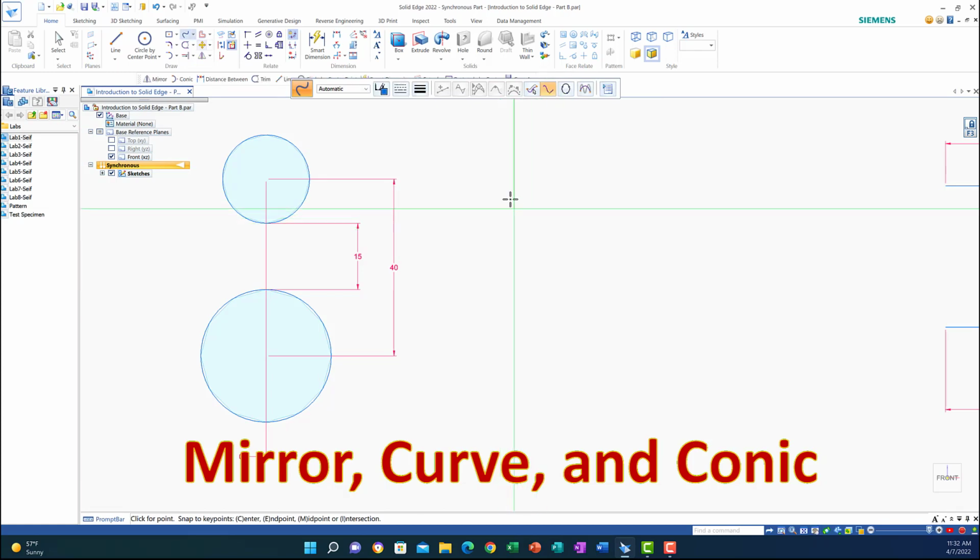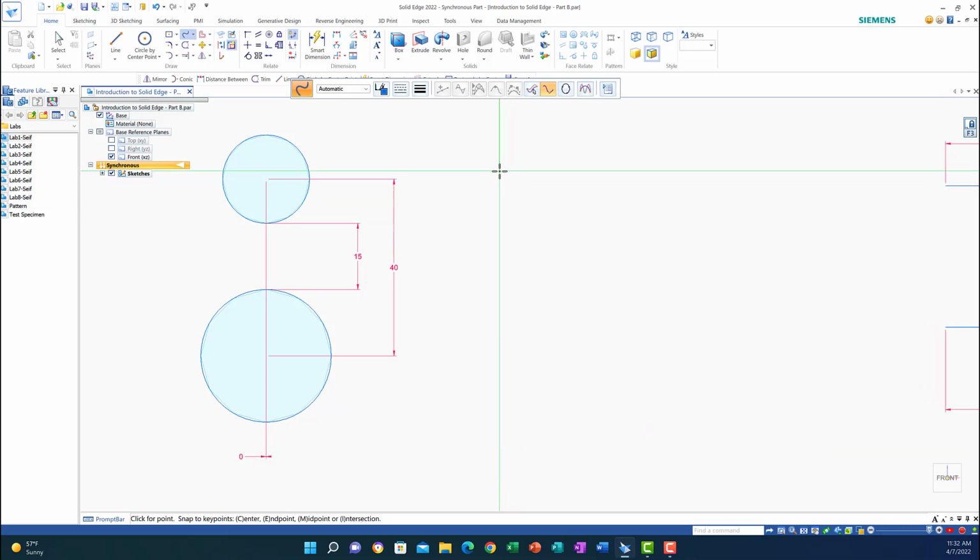What you need to do is just click on the curve feature. Say, for example, I need the curve to start from this point. Now it will go up to the maximum at this point. Then it will go down to a certain location here, and then it will go up again to another one, and then right click to get out.